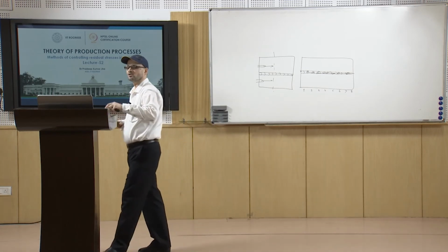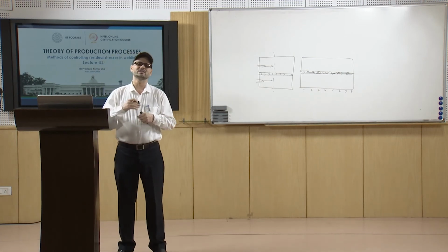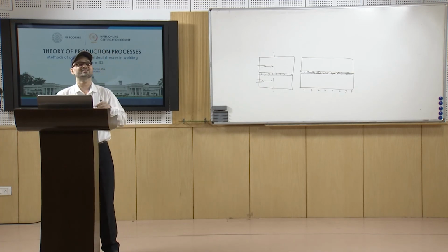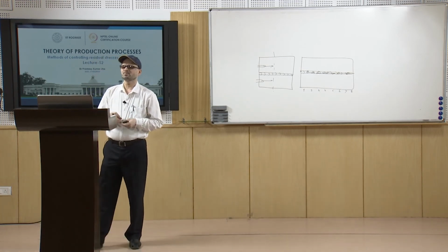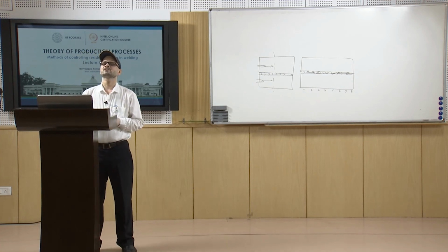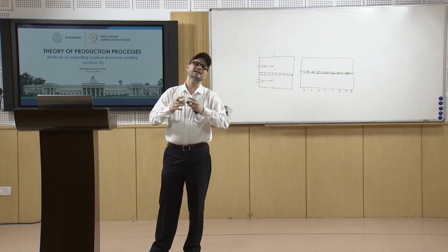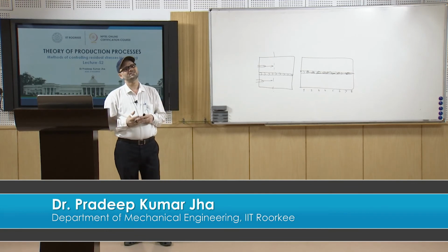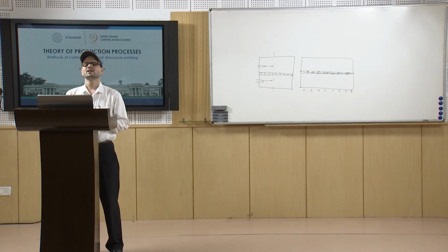So, this way you will have the different attributes of these parameters, and they affect the formation and lowering of the stresses. As far as the design measures are concerned, you must go for the smallest size weld of smallest length. If you have larger sizes, there are more chances of more residual stresses.